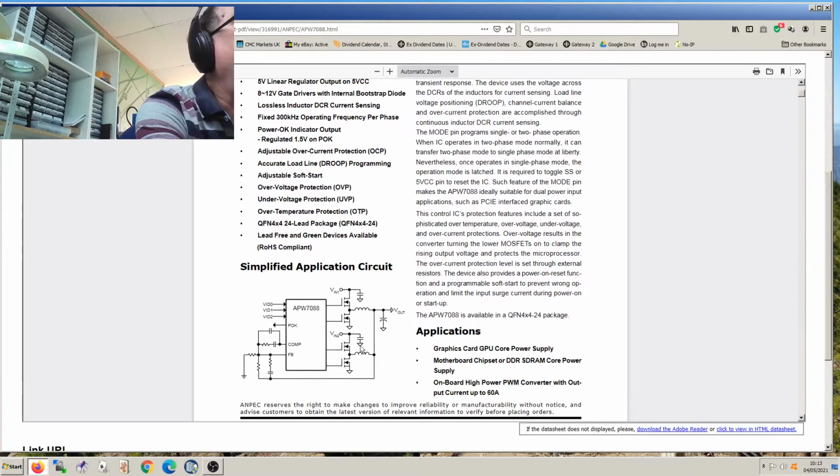So, let me just get in a good position where you can see it nice on the screen there, yeah. So I'm saying this is your example circuit, yeah. And what I'm saying is, I know I've got a low resistance from here to ground, effectively, yeah. So, if I remove this one, then I've removed that path to ground. And if I remove this one, I've removed that path to ground. So the low resistance must be on the other side. If it's still there, it must be on the other side, the load. And that makes sense if you look at this. But it's wrong.